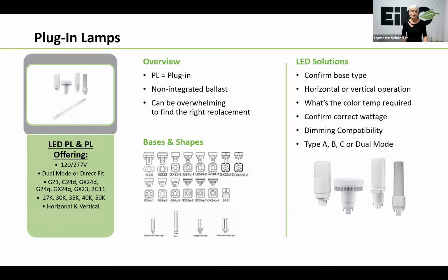So with any LED replacement, it's also important to know what color temperature is required, and make sure you get the right lumen output. The main reason for that, you heard me say it a couple of times, is that too much light can cause a person in the space to get headaches, or they can also get fatigue. And also, it's just kind of overkill and it's costly if you're recommending a really high wattage LED replacement when really you could go with a much lower one. So it's all about energy.